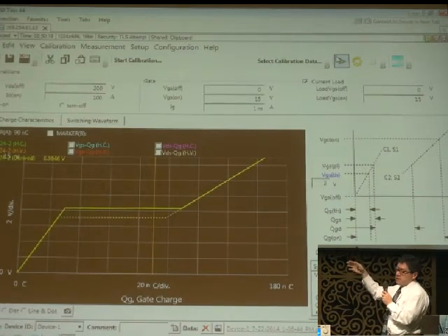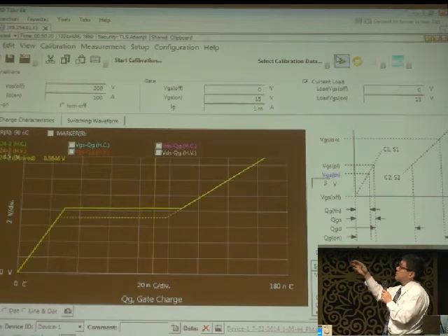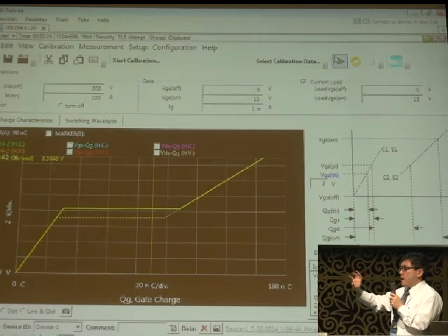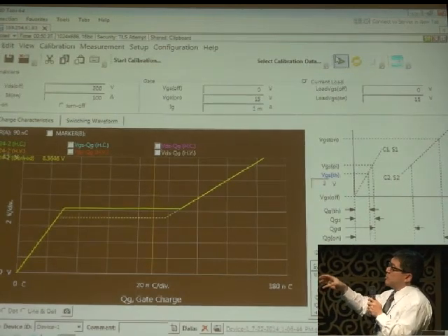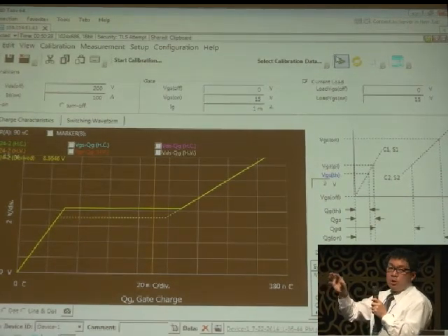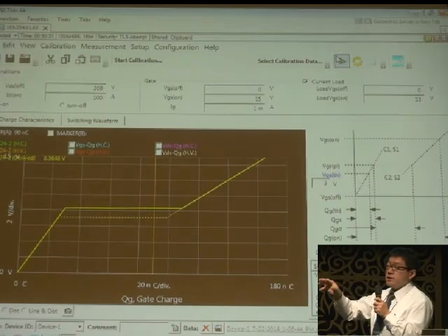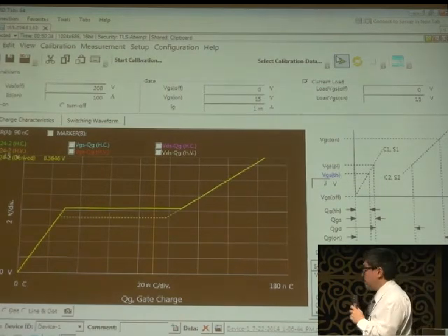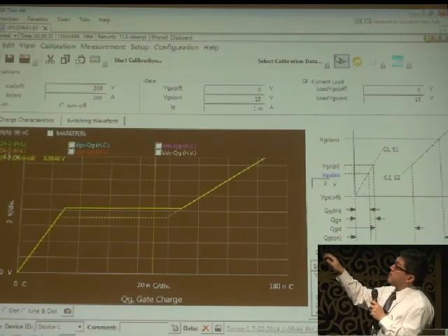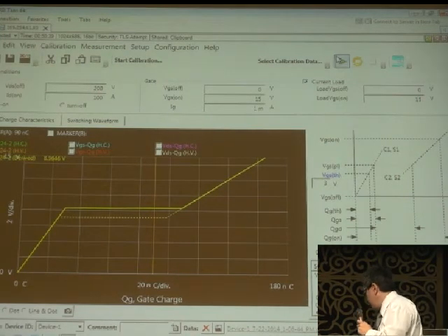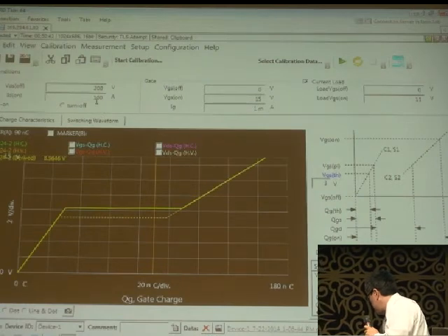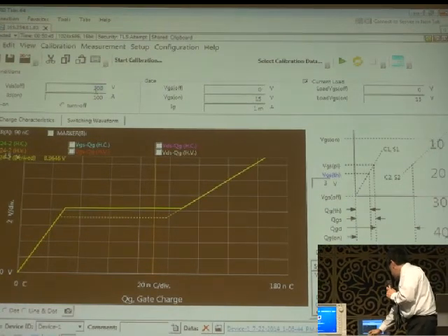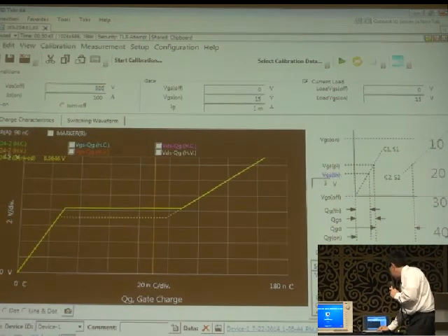When using an existing switching tester or lab setup, it is necessary to adjust the on gate voltage of the load current FET or the value of load resistance to change measurement conditions. But on the B1506A, it is very easy. It is possible to change the measurement condition by changing the parameters here.